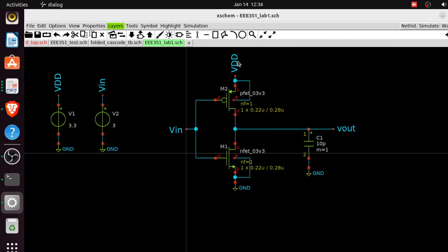For this scheme, there is no GUI for entering this. When you want to do your Spice simulation, you need to give Spice directives. So that's a Spice instruction, a Spice command, and it's in the form of code. For instance, for a transient analysis, you give the directive dot tran. If you want to do DC analysis, say dot DC. If it's AC, dot AC. So you can say that's a command.